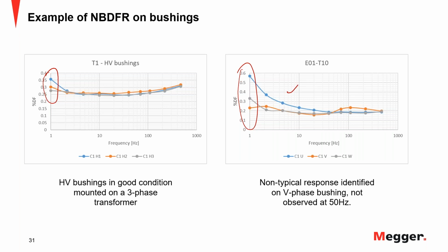My main concern in this specific example will be the orange bushing right here, because that deviation, that change on the shape to what is typical, this is my typical, I always call it like a very serious smiley face, okay? But this one here on this side, as you can see here, there's a non-typical hump, and that might be related to some conductivity, okay, inside the insulation system. Something is wrong, something is contaminating my system. I want to explore in more detail this bushing, okay? And that's something that probably I would have missed testing only my 60 Hertz value here.